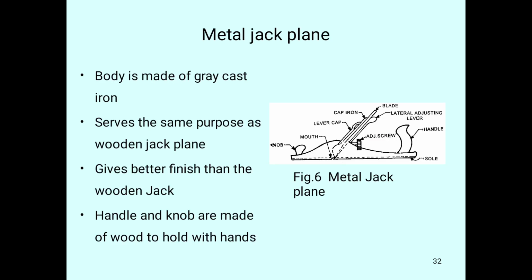The knob is held with the left hand and the handle is held with the right hand. So by moving the plane we can remove the unwanted material from the wooden workpiece.